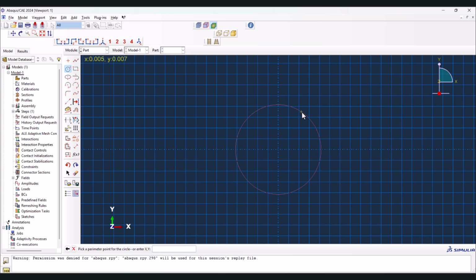If you put the point somewhere around like here, when you want to mesh the model, you would have this part separated from this part and this part, so you would not have a good mesh. So I hit Ctrl Z, and once more create the circle here, first point, and the second point must be here on one of these vertical or horizontal axes.